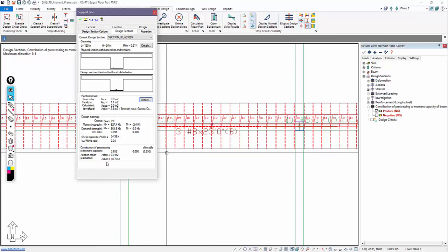At this particular section, the user would actually need 10.7 square inches of reinforcement to dilute the capacity to 25%. So the user could technically take a weighted ratio of the amount of pre-stressing steel with respect to its strength and ultimately reduce this amount of PT potentially, or add this amount of rebar as a direct result of the check being made.